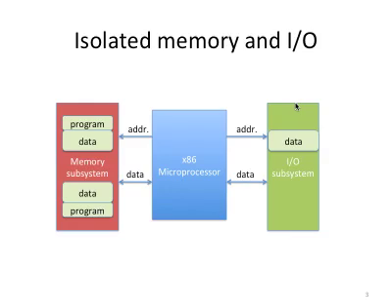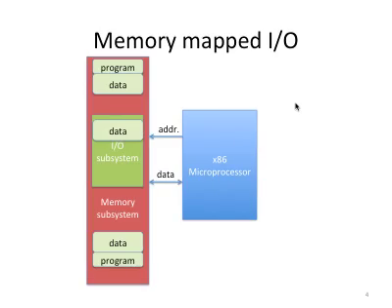You use IN or OUT for x86 processors to access data in the I/O subsystem. And you know what data you're going to access: is it data stored in memory, or data stored in I/O space? So you can do some optimization in terms of the interfacing for these two different systems.